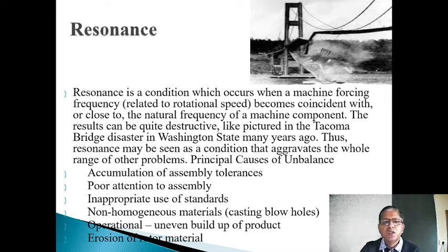Such failures are called resonance, and it is up to the design engineers to keep the natural frequency of the structure far away from the excitation frequency.